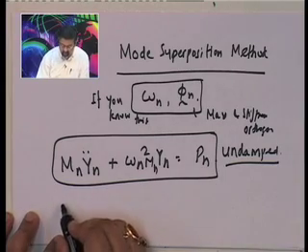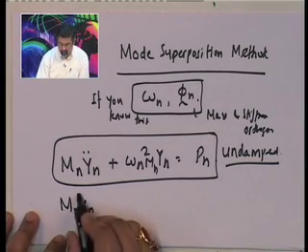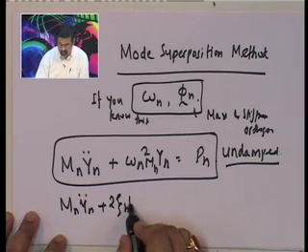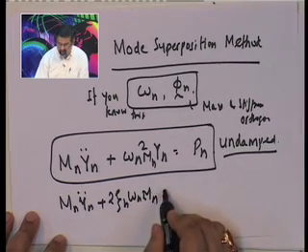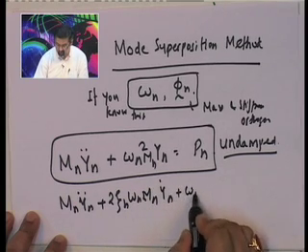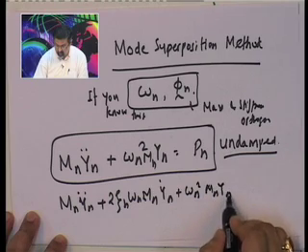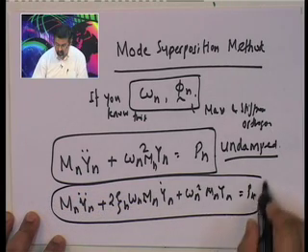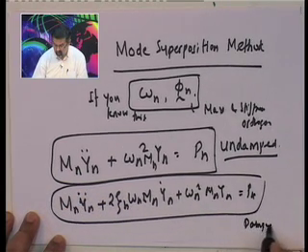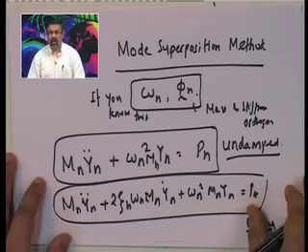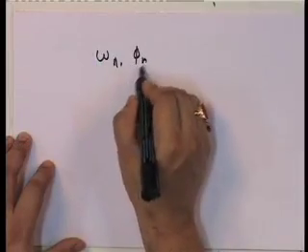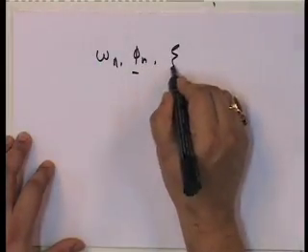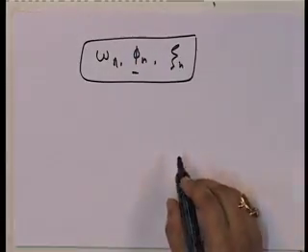And I say that the corresponding damped system, with an equivalence from the single degree of freedom system, would look like this. This is what a damped system would look like, and we also said that along with omega n and phi n, for the mode superposition method, all we need to do is define this parameter.